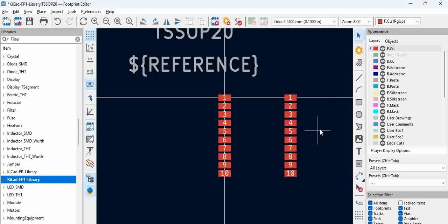So the next thing we have to do is include a solder mask indicating the first pin. So before doing that, let us try to draw the CourtYard. CourtYard basically indicates how much distance a component placed adjacent to the component should have, right?